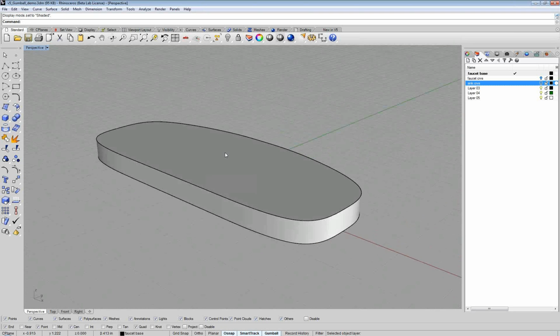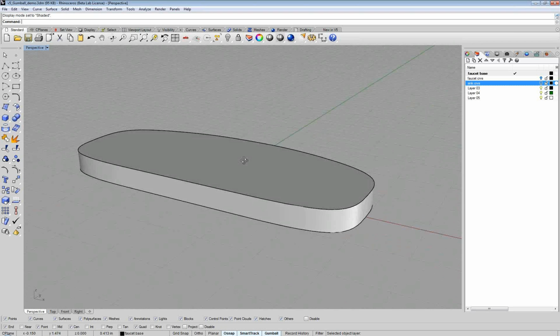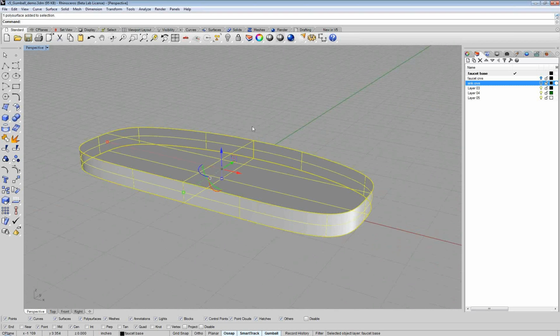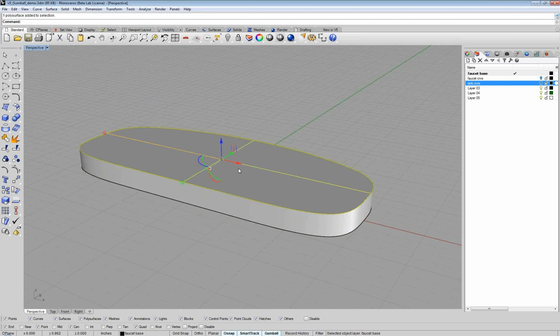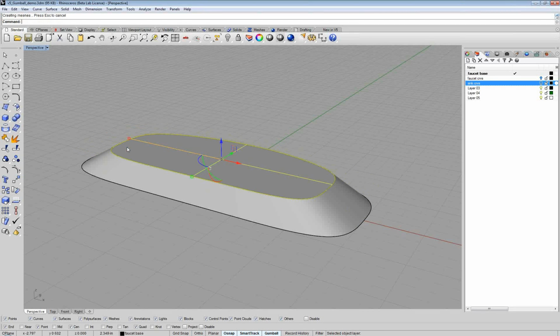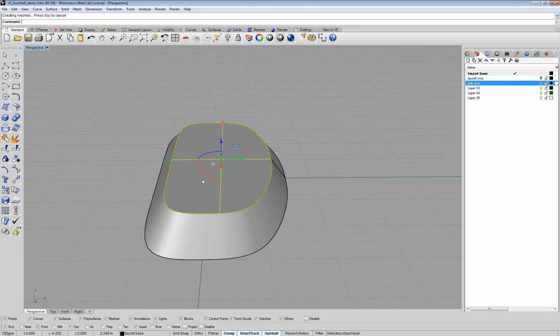After I do that, I actually get a solid object just from a single planar curve. Now the fun thing is that if you just left-click on this, you select the entire polysurface as you normally would in Rhino. But if I hold down the Control and the Shift key and left-click, then I'm sub-object selecting this top trimmed surface. I can then start to scale by dragging on the scale manipulator for the Gumball. If I hold down the Shift key, I can scale in both X and Y at the same time, and then release the left mouse button, and I've created this trapezoidal type shape.